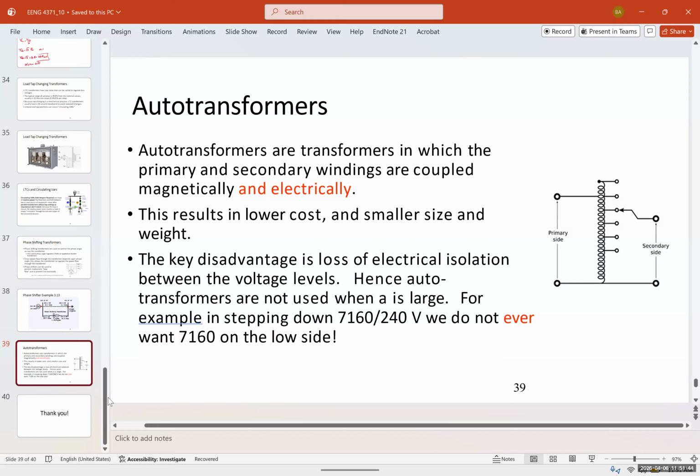That works perfectly fine. You have some limitations because frequency here is 60 hertz, over there it is 50 hertz. The system would still work, but if it's a fridge, for example, with a compressor, you're going to have knocking on it. It's going to last much less than if it's designed for 50 hertz. But other electrical devices, like a dryer, you won't have any problem. So for small changes, an auto transformer works perfectly fine.